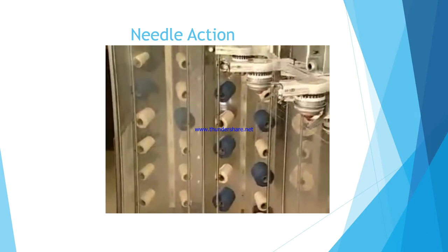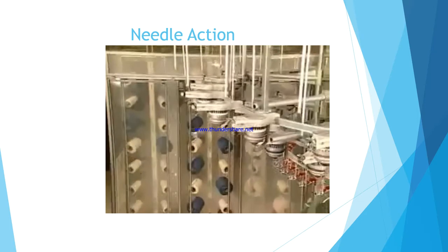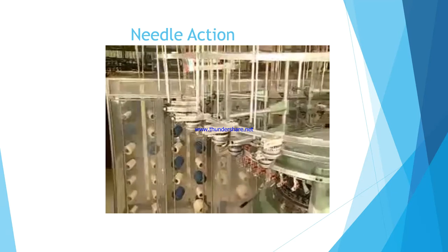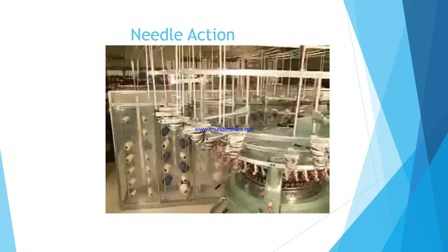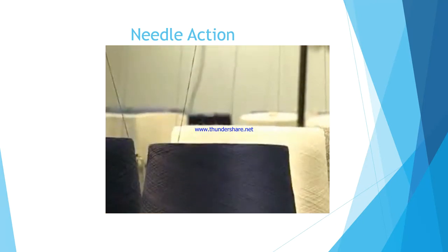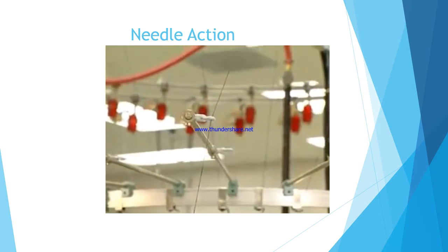To make it easier for technicians to service the creels, it is more usual to find creels located at the side. In this position, less lint falls into knitting elements. Larger packages can be used, and more feeds can be placed on the machine. Whether the creel is at the side or top, the principles for circular knitting are the same.